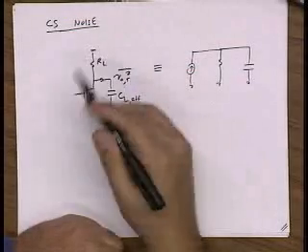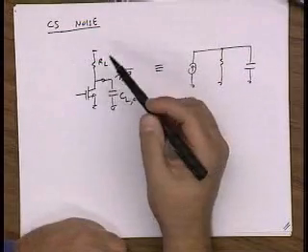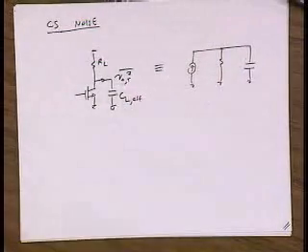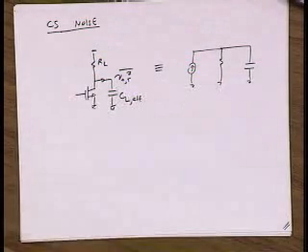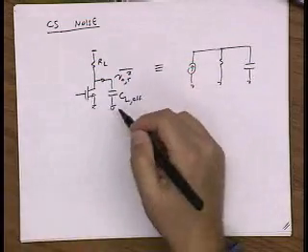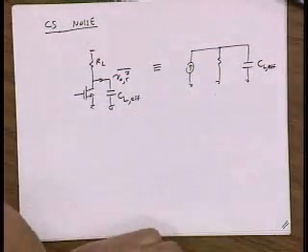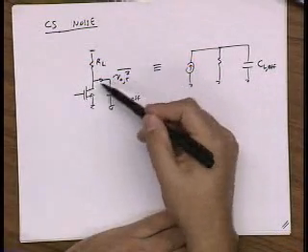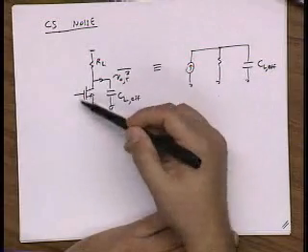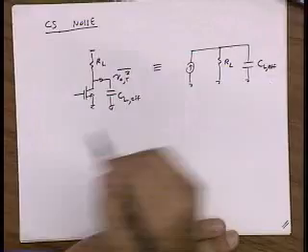That means I don't have to worry about the details of the amplifier and all its poles and zeros. I'm going to assume that this amplifier has been properly designed so all its non-dominant poles fall high enough that they don't affect the stability of this amplifier. So really, this is the only capacitor I need to consider. I'll put that over here, CL effective. Well, what's the resistance looking out from this capacitance? It sees the output resistance of this transistor, and it sees RL. Let's say RL dominates.